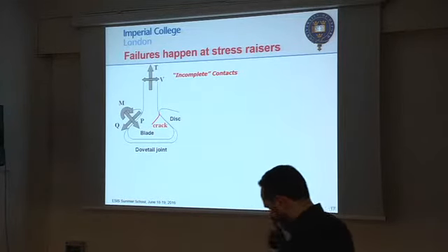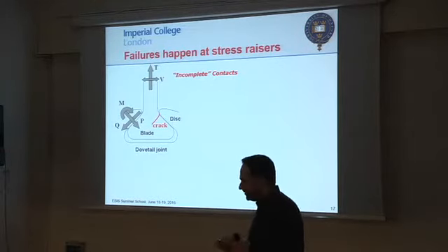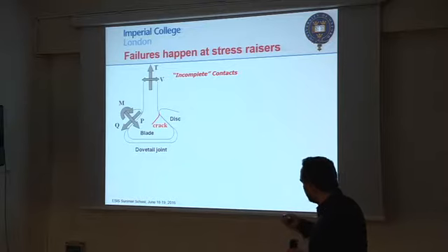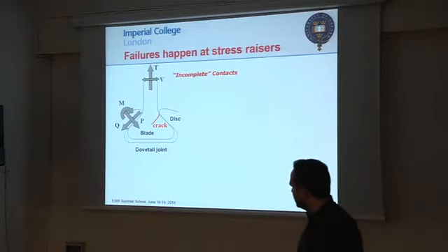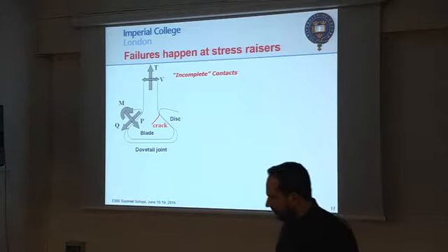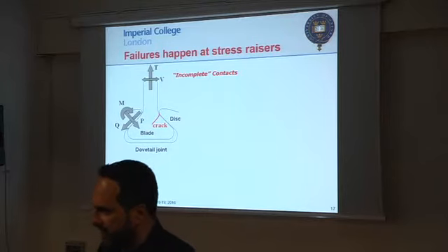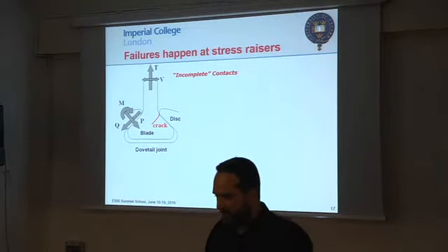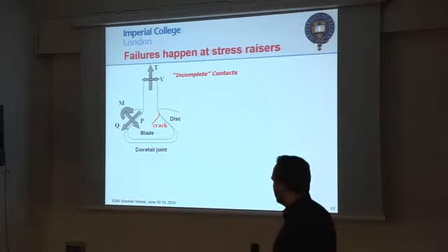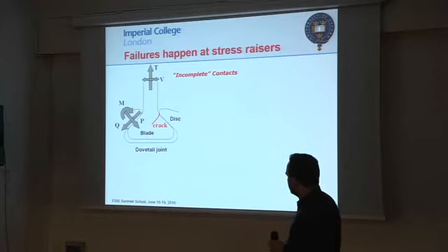So I said, okay, let's say I have a blade and I have a disk, and I want to replicate how the crack starts in that disk. And I know, you start looking at words in here that appear with definition. So this is an incomplete contact, and I'll explain to you what it means properly later. But the idea is that I know that cracks will start there for various reasons.